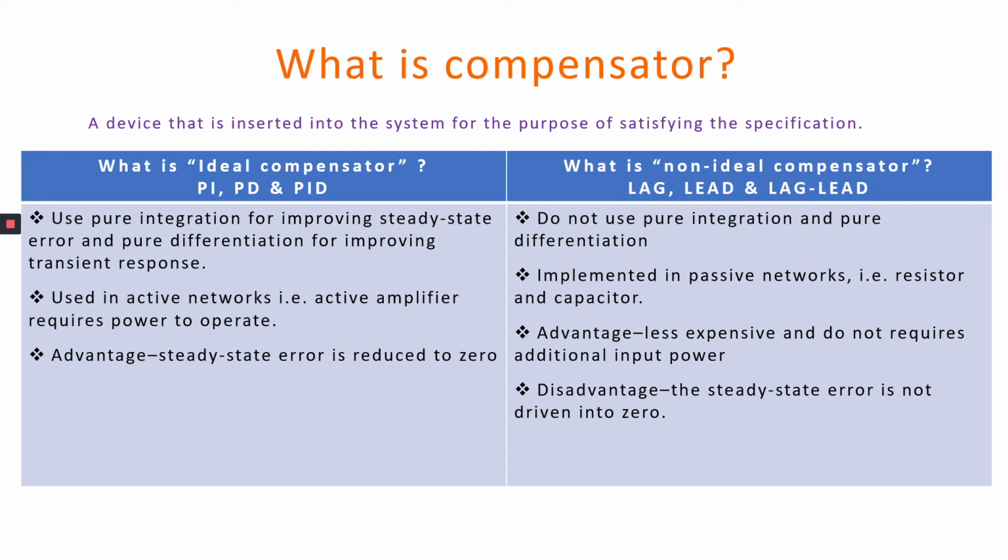One of the advantages of compensating the system in this way is that additional poles and zeros can be added at the low power end of the system before the plant. Addition of compensating poles and zeros need not interfere with the power output requirements of the system or present additional load or design problems.